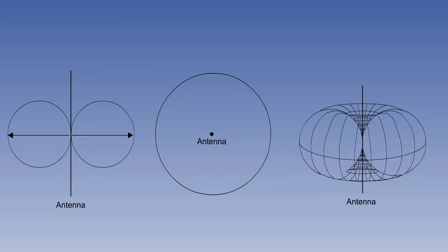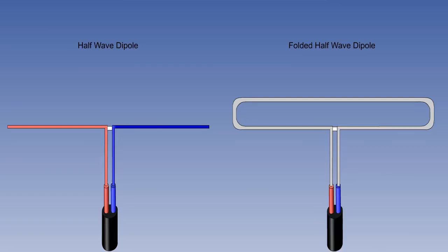The pattern or polar diagram of the emission is called toroidal. It looks like a fat donut with the antenna in the center. Some half-wave dipoles, known as folded dipoles, have a second conductor joined to the ends. These are used to achieve a broader band of frequency emission, such as the aviation band from 118 to 136 MHz, rather than targeting a specific wavelength.